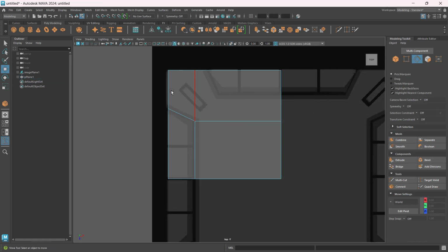On to the next one is the top one, that top detail there. I can do another connect. I can choose W, Enter, and then W, so that I can move the vertex here, for example, and then I can just adjust the slide here. There. So now I have that detail done, right? Okay, so now that I have that done, I can select these, for example, and I can delete them.